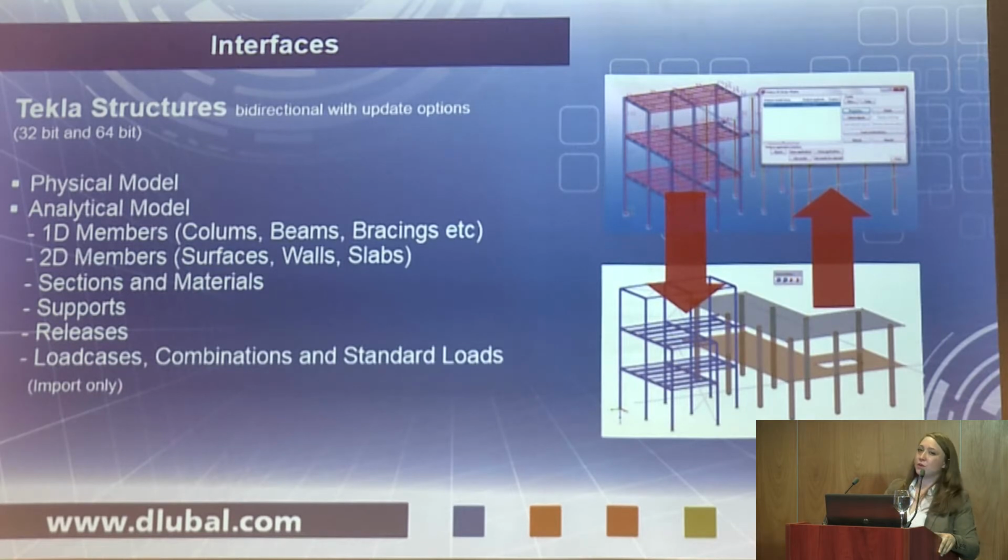And as was said before, we are able to export and import the physical model and also the analytical model. As you could see, the physical model is the model that you are building in Tekla, but it is not equipped with knowledge about the static and mechanical model. So it doesn't have any kind of support, any kind of loading, any kind of releases. But the analytical model gives us the opportunity to import all this information from Tekla Structures.